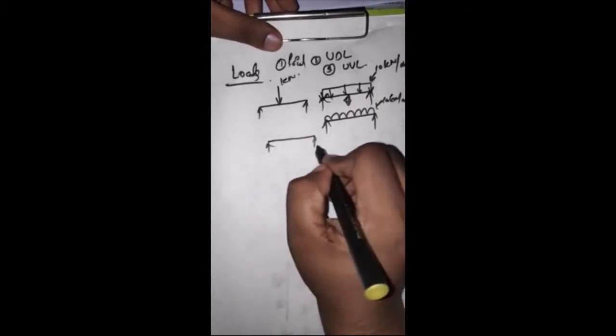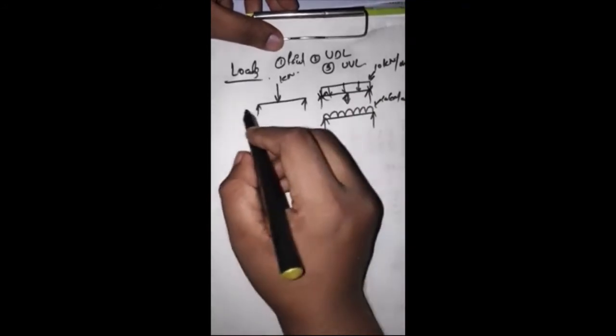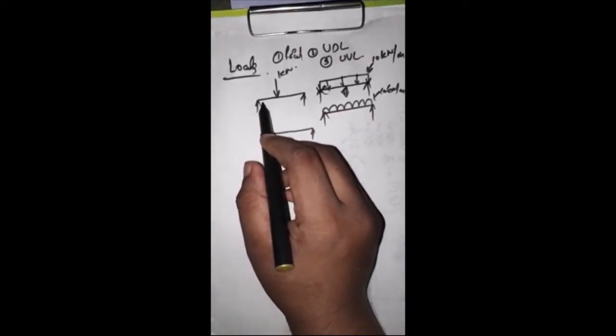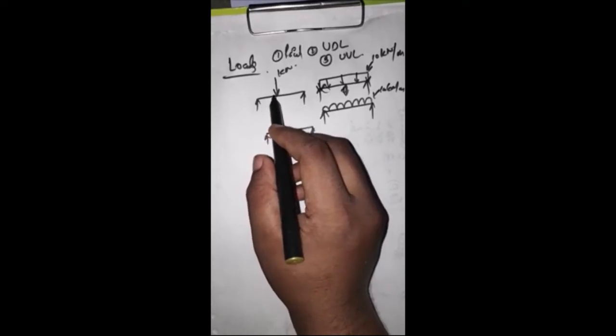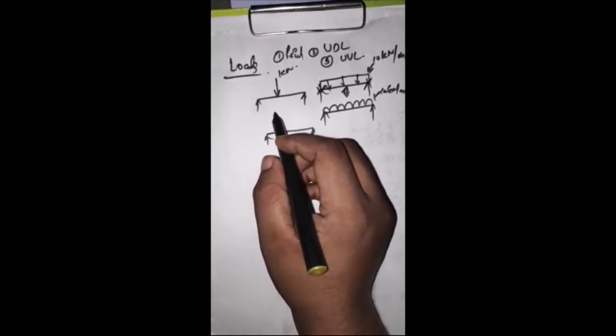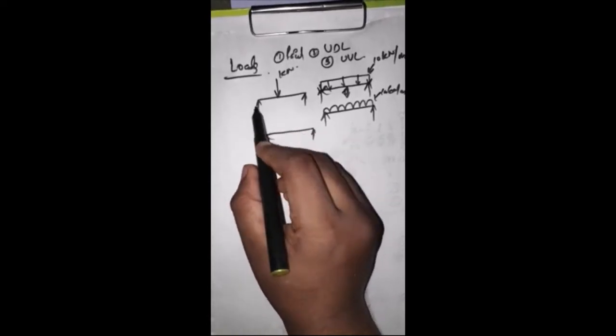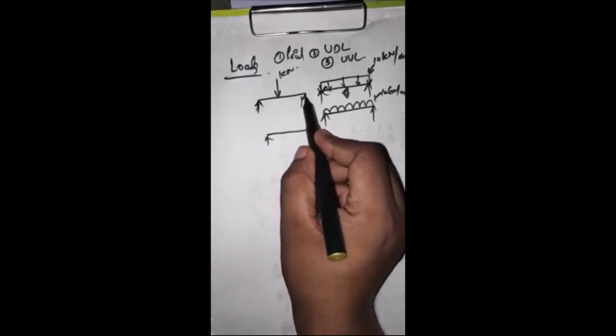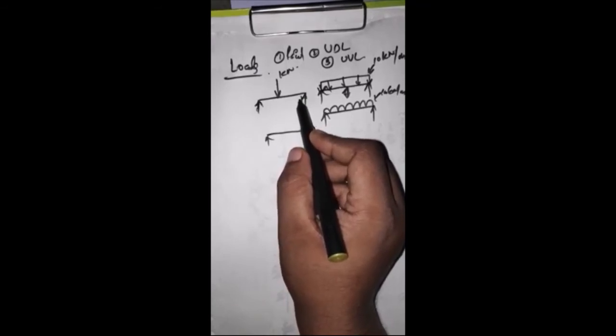I am not talking about the supports. If nothing is given for the support condition, we know that 3 supports are there: fixed, hinge, and roller. Sometimes the support is represented by only an arrow. That means there will be only a vertical reaction.